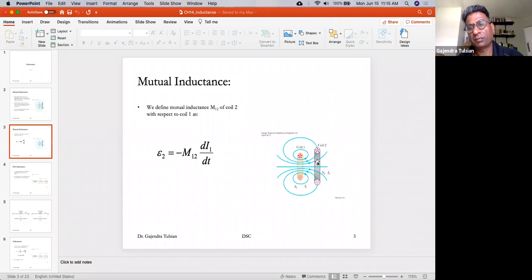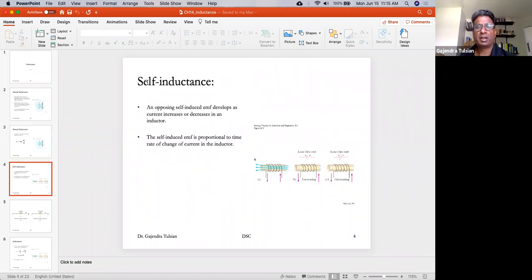Now, if of course the two circuits are far apart, then this number will be smaller. So the mutual inductance depends on the proximity, the configuration, the areas, and all that kind of stuff. So this number is hard to calculate other than for very symmetric cases. But anyway, that's the mutual inductance. Again, now we'll mostly talk about self-inductance.